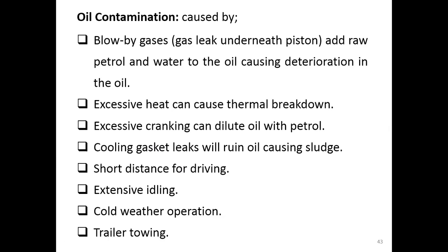Under lower temperature, the oil viscosity goes up. So high viscosity will create a problem for the engine to start under cold weather operation.